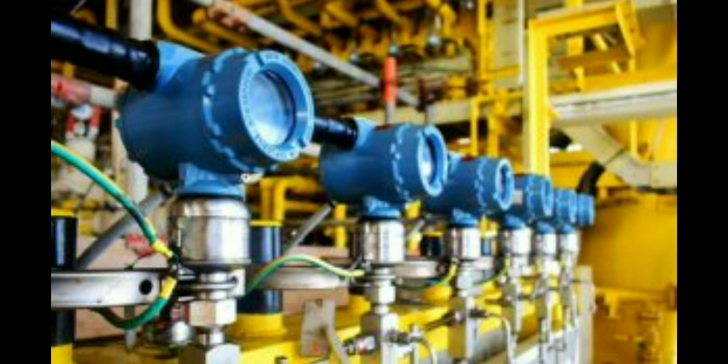Let us look at the disadvantages of an absolute pressure transmitter. Absolute pressure transmitters can be more expensive than gauge pressure transmitters, primarily due to the precision required in their design. Absolute pressure transmitters are not suitable for measuring pressure above atmospheric pressure. So, for higher pressure applications, gauge or differential pressure transmitters may be more suitable. The measurement of absolute pressure requires careful calibration and design due to the absence of a natural reference point,